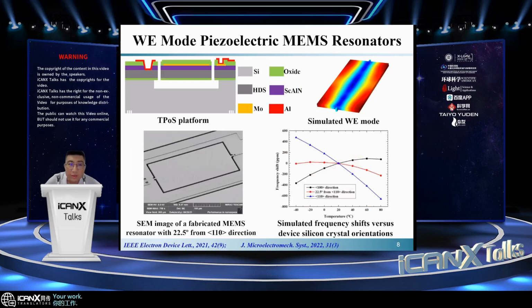In our work, we designed a Lamé extension mode piezoelectric MEMS resonator. The resonator is designed based on a thin film piezoelectric on silicon platform. And we tune the resonator structure alignment. So for example, the resonator is aligned 22.5 degrees from the 110 direction. Thus, we can have a better TCF performance.